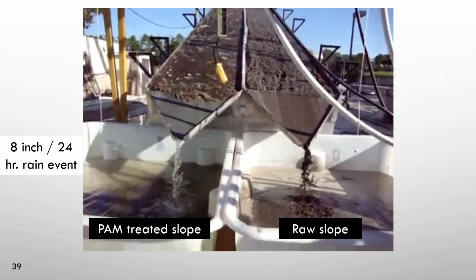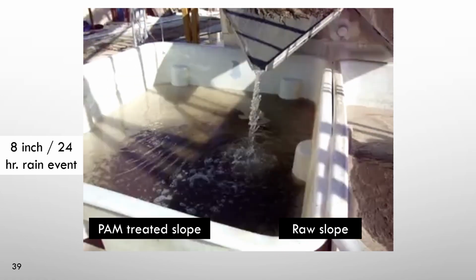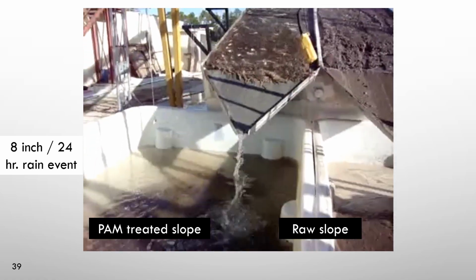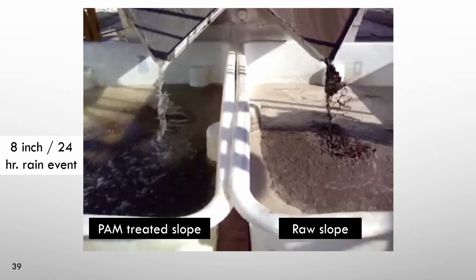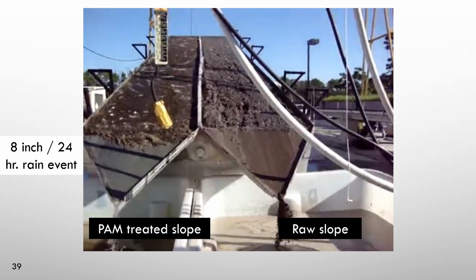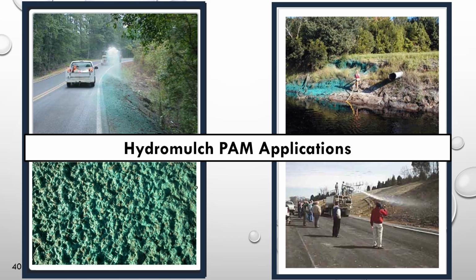It's holding that soil in place, flocculating those fine particulates. There is some escapement there, but for the most part, if that wasn't discharging directly into a water body, those would also be collected downslope and attached there as well. So again, polymer enhanced soft armoring is very, very effective at holding all the material in place and improving runoff quality. Now, polymer enhanced soft armoring can be applied and used in a number of ways.